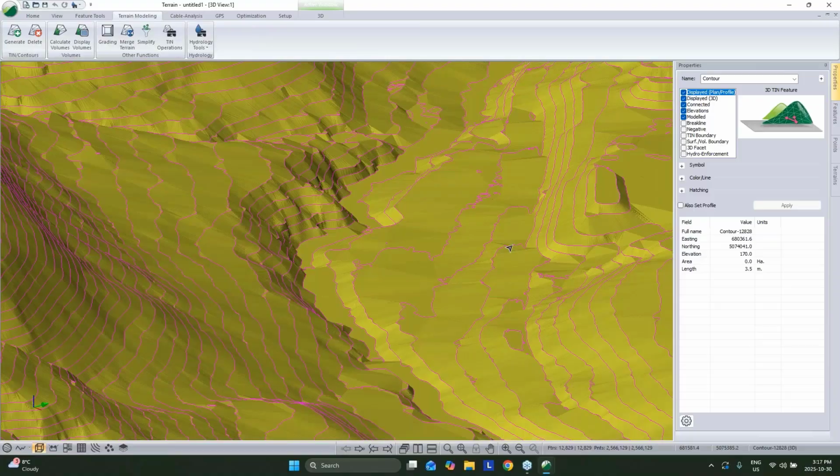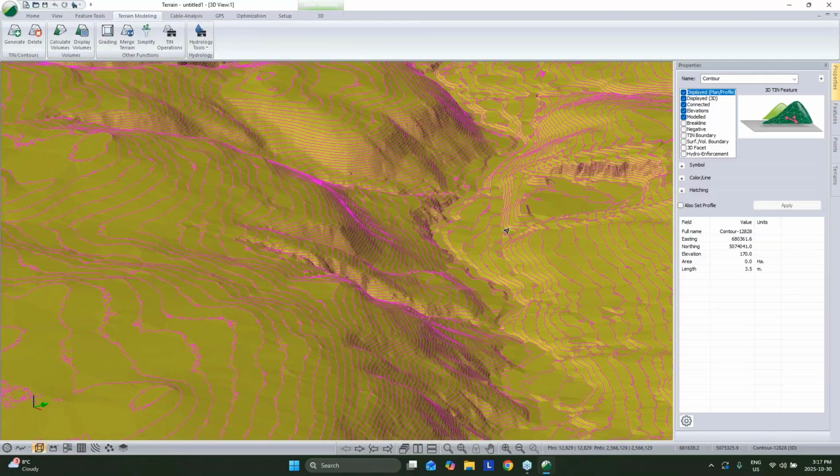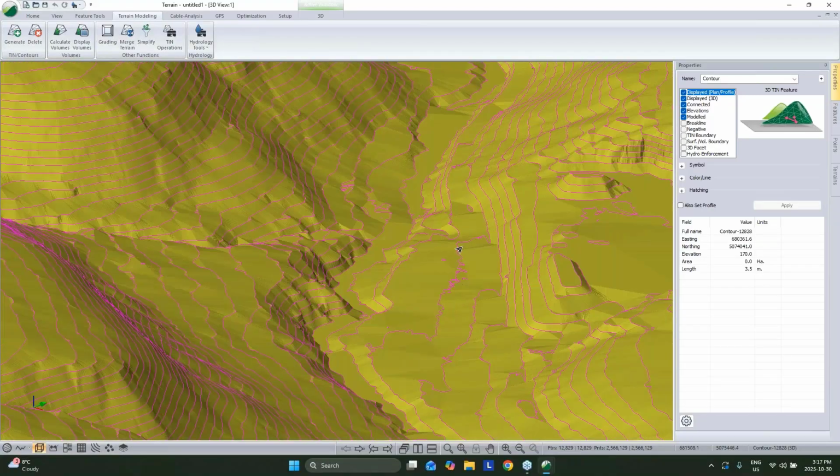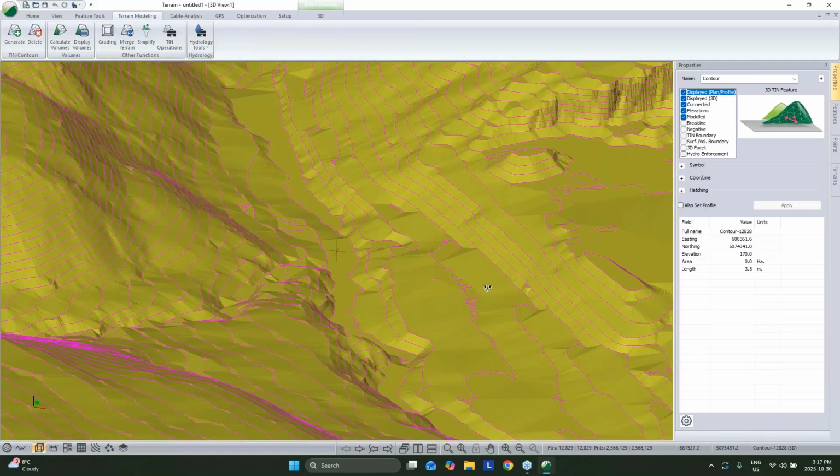And of course, if you're using our software, there's a good chance you're doing some kind of corridor modeling. And contours are defining between elevations, and they obfuscate where other features may be, like existing roads and what have you. So not ideal, and it really is just that. It's not ideal. If it's the only thing you have, or it's the best source of data that you have, well, it's certainly better than nothing. But if you have access to, as Aaron said, the raw survey data, whatever format was used to define these contours, it's usually a better bet.